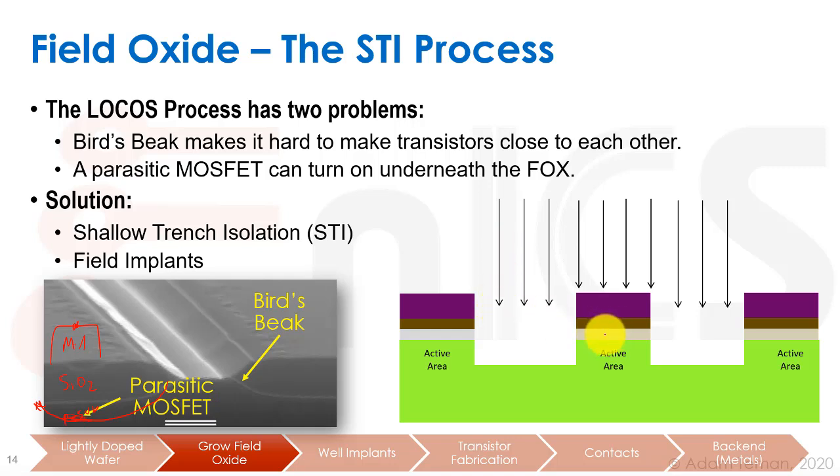We're going to etch away the silicon that was before. The photoresist is protecting us from the etch, because the etch is like some bombardment of some material that's eating away the stuff that was above. And we keep on etching until we trench a hole into the substrate. So that's why it's called shallow trench isolation, because we actually dug into the silicon this time.